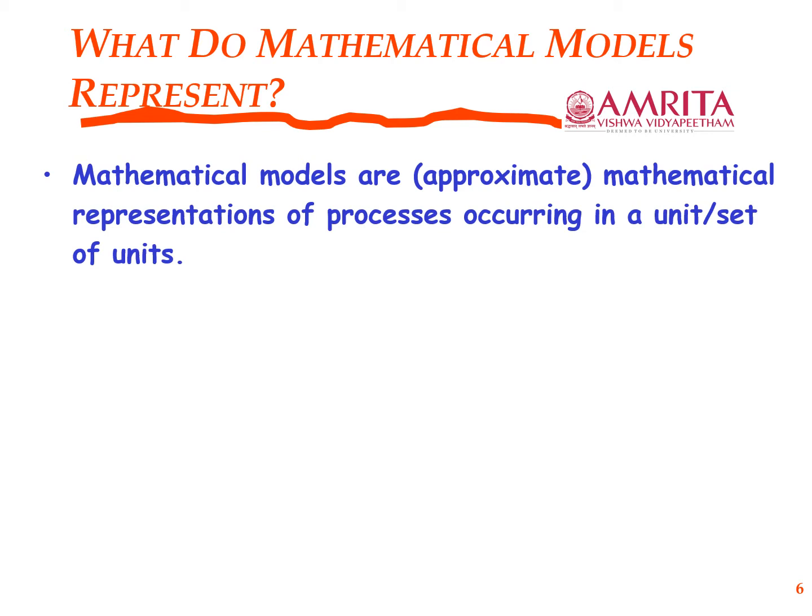It is one of distillation, where the low volatile component is volatilized and moves upward from the bottom of the unit to the top of the unit, and that is predominantly in the vapor phase. And the heavy components, which are predominantly in the liquid phase, flow down. The less volatile components, rather the heavy components, condense from the vapor phase and get collected, accumulated in the liquid phase, and they keep coming down.